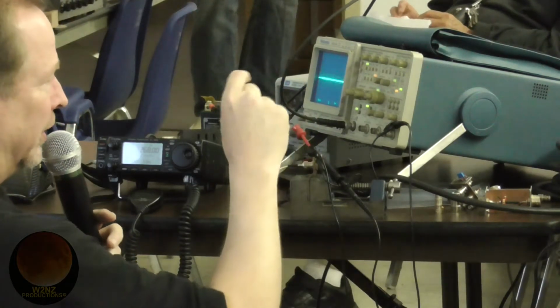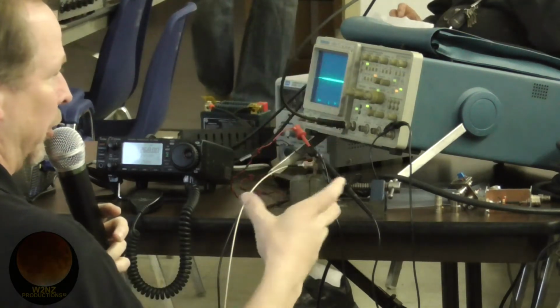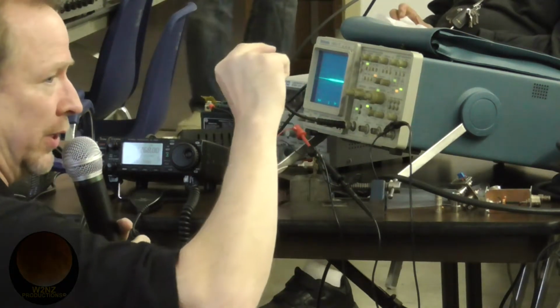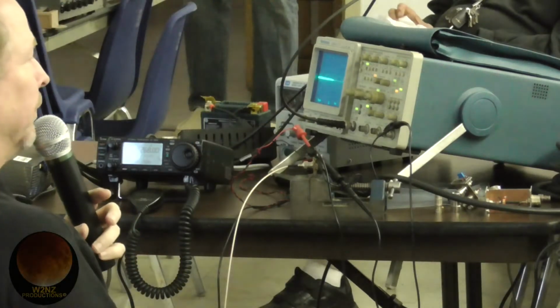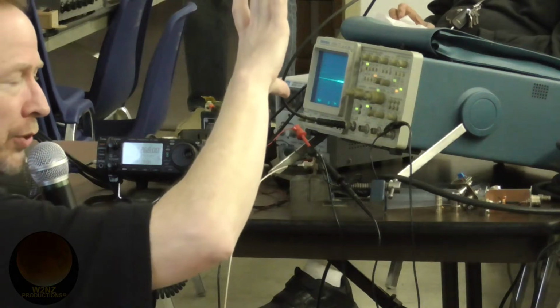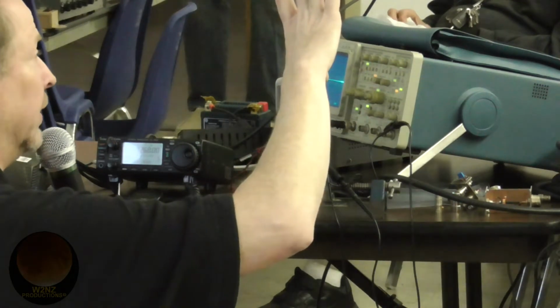So to get really good modulation fidelity on an AM transmitter on a modern 100-watt rig, you actually want to cut the unmodulated carrier output to 25 watts. So that now when the amplitude doubles, for 100% modulation, that'll be your 100 watts PEP.